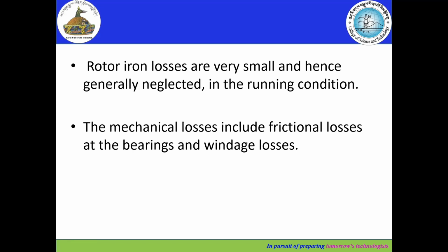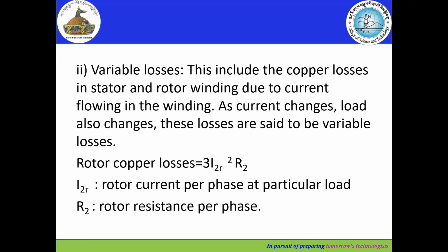And as you all know, in the rotor there are rotor copper losses and rotor iron losses. The rotor iron losses are very small and hence generally neglected in the running condition. The mechanical losses include the frictional losses at the bearing and windage losses.